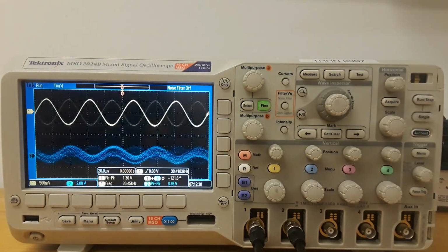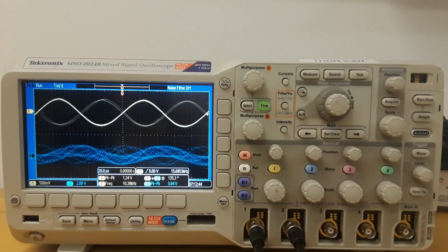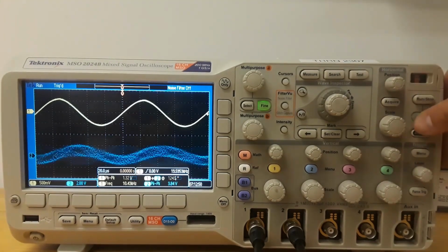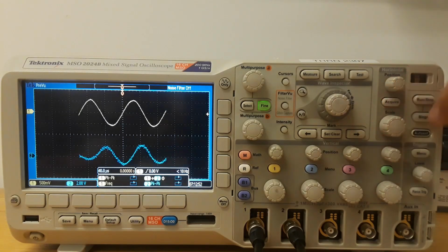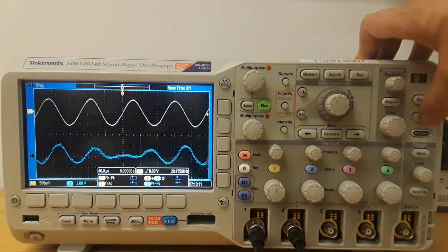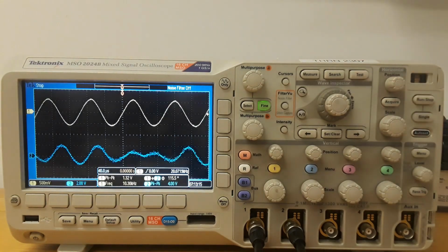Now let's take a look at what happens when we've got 10 kilohertz up there. We'll just drop this back down once again and take a look at our signal. And that oscilloscope certainly looks interesting, doesn't it? Let's zoom in a little bit here, maybe take some single looks, change our scale, and you can see again the output wave there is very different from the input wave. It looks like there's definitely some low frequency noise going in there that's canceling out some of those peaks.